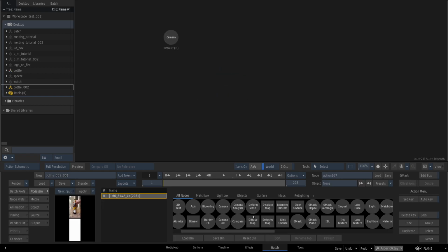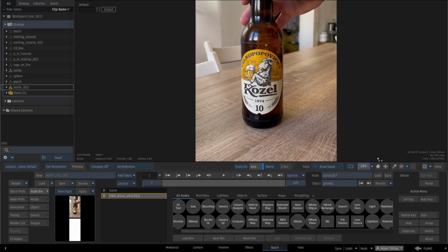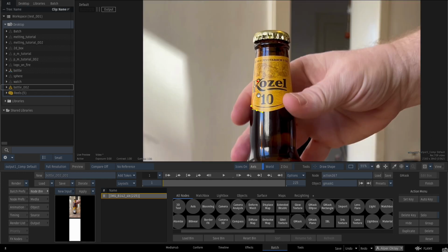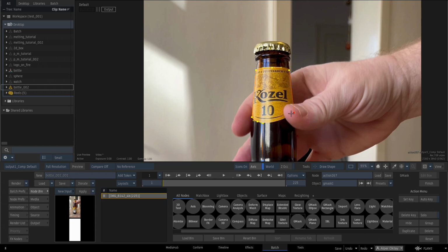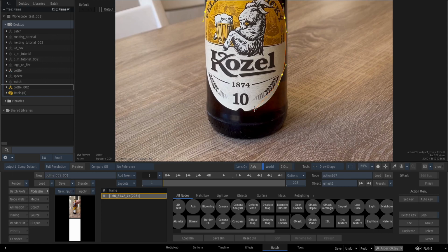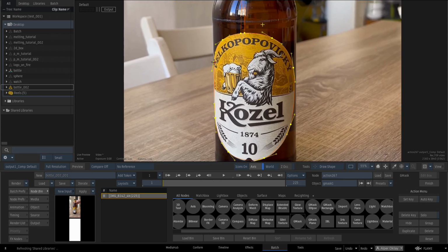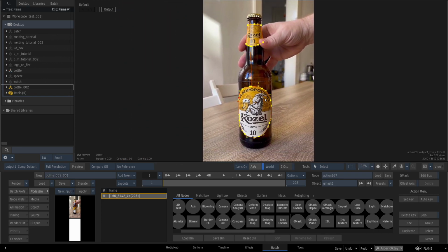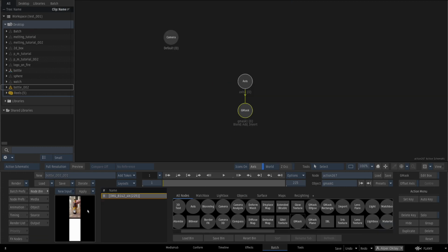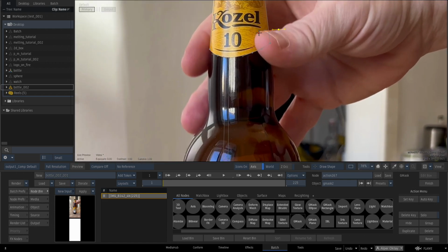First thing you should do is masking the area that the camera analyzer will use. I couldn't find an option to combine two separate masks together. Because of that, I used a single mask for the center label and the label at the top. You should select Invert for this mask. I used two masks for fingers to exclude the area.